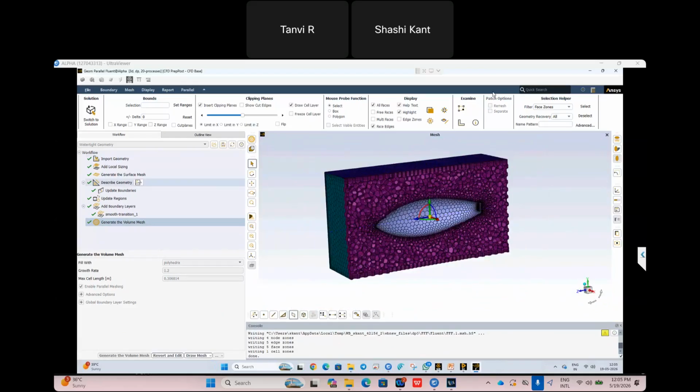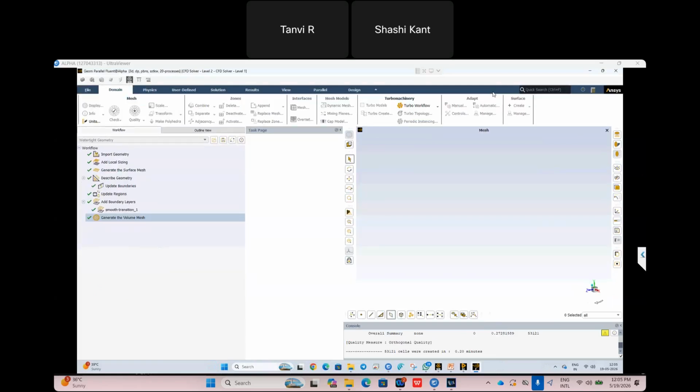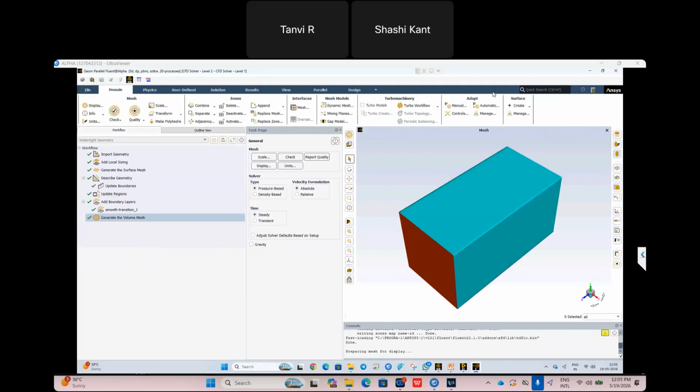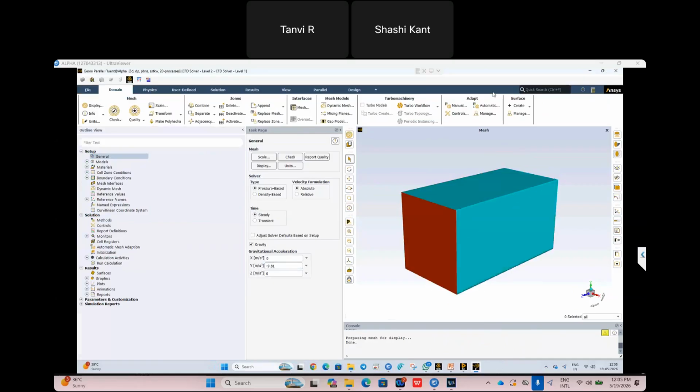Okay. Now I want to jump to the CFD Fluent case. So just click on this and check sign. The meshing will be transferred for the Fluent boundary setup. So now I want to capture gravity, minus 9.81, and I want to see the response of the gravity.